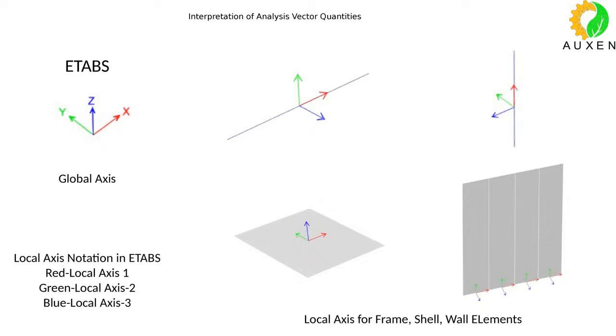So if you can see a beam along the length, which is the axis that you see, which local axis? So along the length you see it's the local axis 1, isn't it? Then in the cross sectional directions you will have the axis 2 and 3, local axis 2 and 3. Similarly for the column, if you see along the length of column, you see local axis 1. Along the cross sectional dimensions you will get local axis 2 and 3.